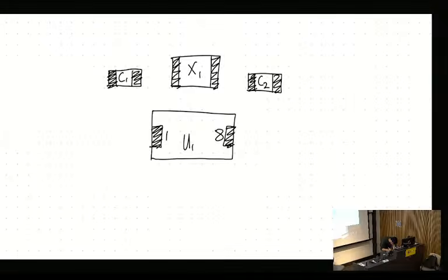So if I draw this, I have a signal that goes to this capacitor, like that, and goes to the crystal there. As an example, the trace width doesn't matter too much, because that depends on other factors, but it's not relevant here.